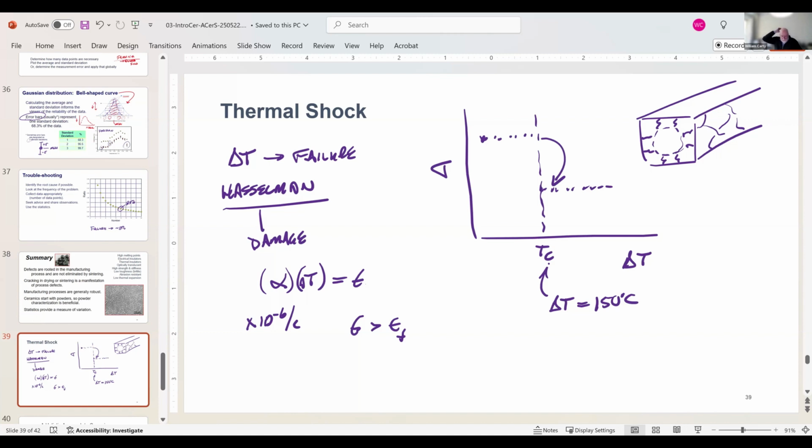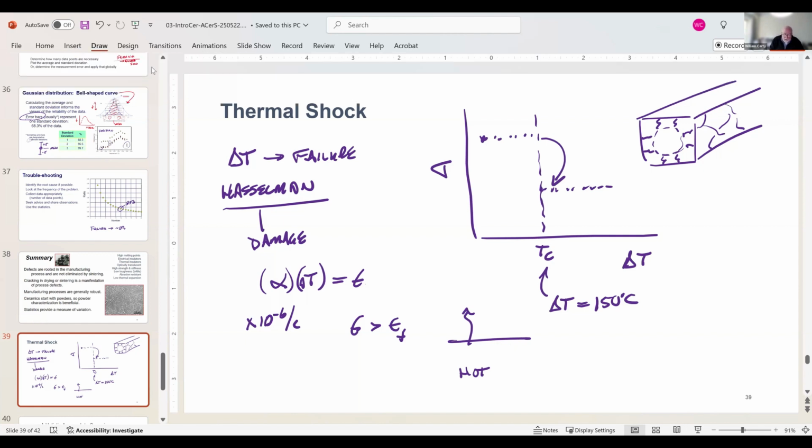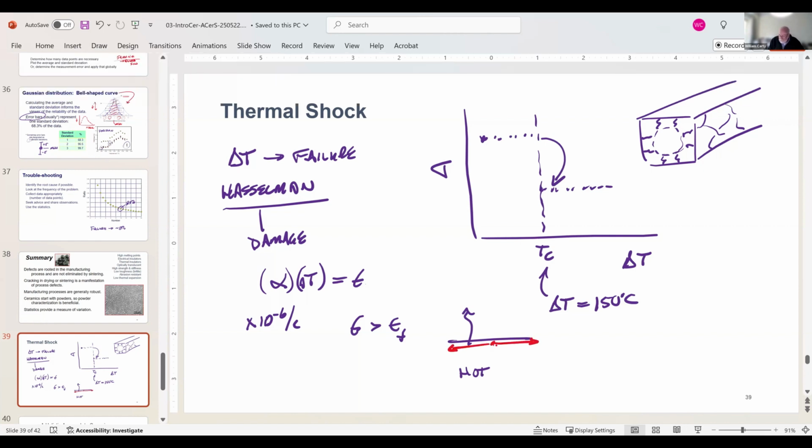So the way that it works is that we have a cooling from the surface, right? But the interior remains hot. And so that puts the surface then in tension. I drew it in compression. But what happens is because it is contracting, it places the surface in tension. I got it right. The inside remains in compression, which is fine, except it's irrelevant. So when the strain associated with that tension, which is related to this alpha times delta T, exceeds the critical point, the system fails.